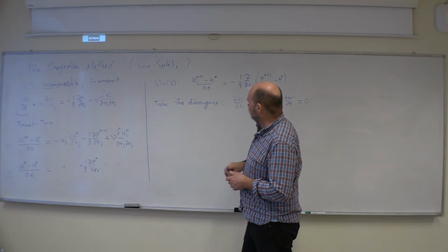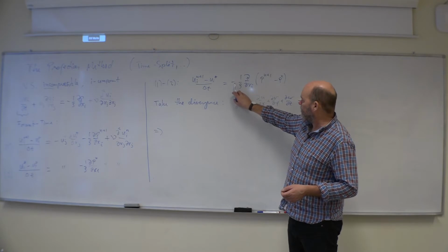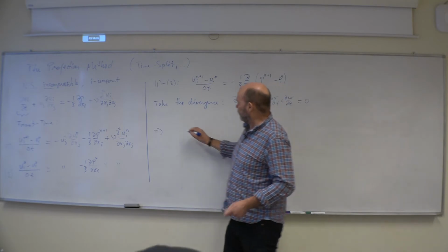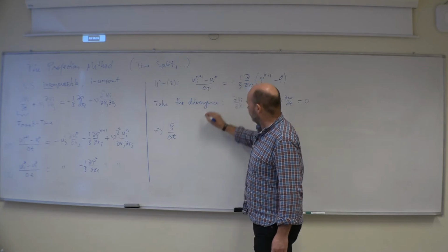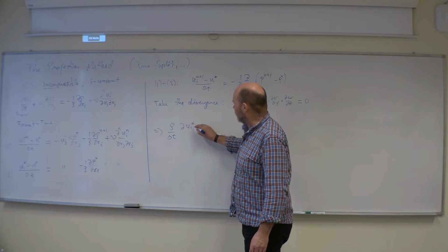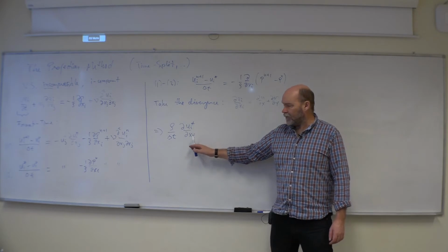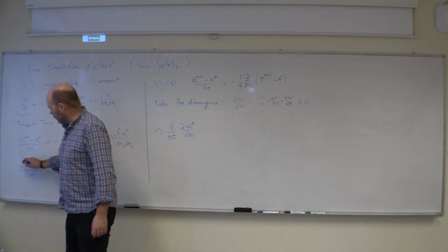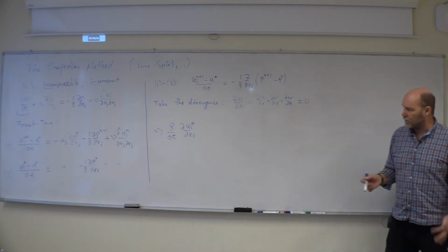So what are we left with? I will have a minus and a minus. The delta t I can keep here, and rho goes up here, so it should read something like rho divided by delta t, and then here I will have dui star dxi. That is the divergence of this tentative velocity field, the one I created very easily, a fully explicit equation for it. So it's easily found.